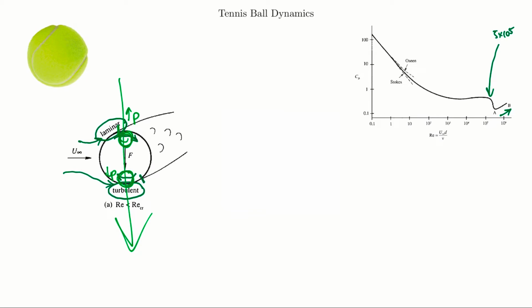But this case does show us that what's happening here is the opposite of what the Bernoulli effect would predict in terms of forces at these low Reynolds numbers. So that's what shows us that for these spheres, it's likely that these boundary layer effects that we're describing here are more dominant than the Bernoulli effects, which we saw in the cylinder. And so that's what we can learn from this low Reynolds number case, about which of these explanations has the more dominant effect.